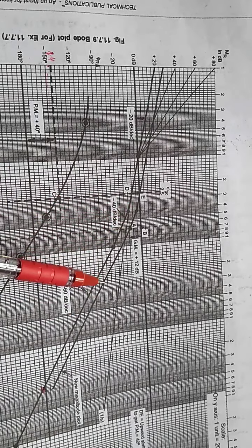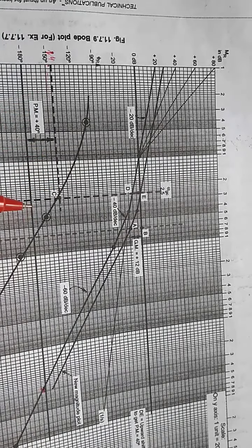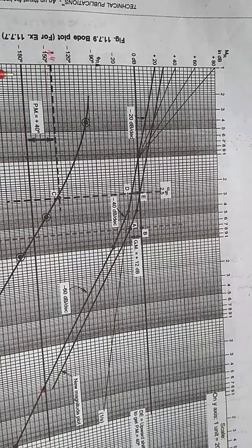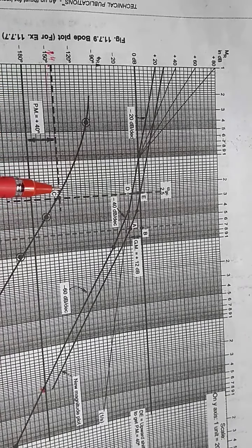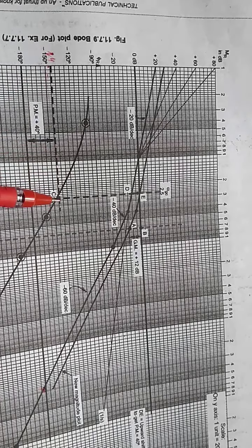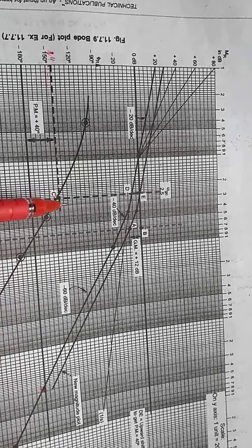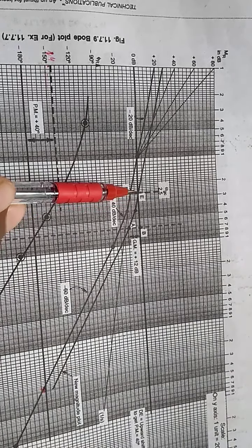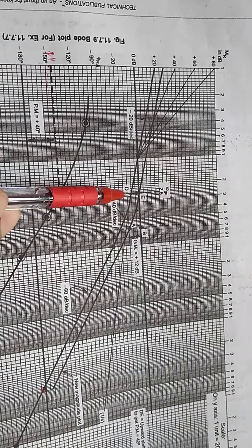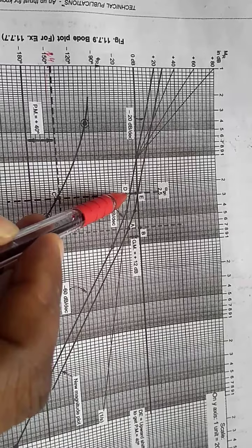While drawing this plot, draw the horizontal line for the phase margin, which is 40 degree. 40 degree means from the reference, 180 minus 40 means we will get 140. Mark 140, horizontal line for 140 degree. So this is the intersecting point. Consider this intersecting point projected towards the magnitude plot, from the actual Bode plot to the actual magnitude plot to the new plot. So here we will get the points.